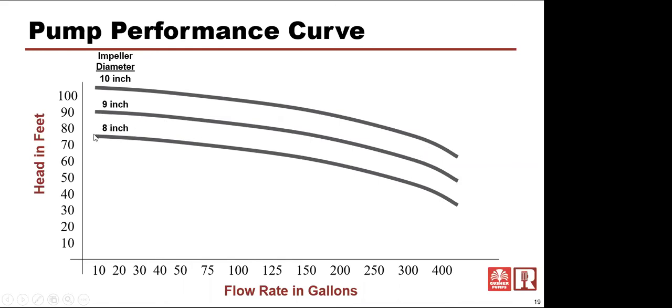And there's always some variance in curve performance, albeit small, because of the clearances within that casing. Remember, I talked about recirculating water from the low pressure side to the high pressure side, where the cutwater is. There are always going to be some losses that are not 100% consistent, depending on the spacing of gaskets and specific clearances.